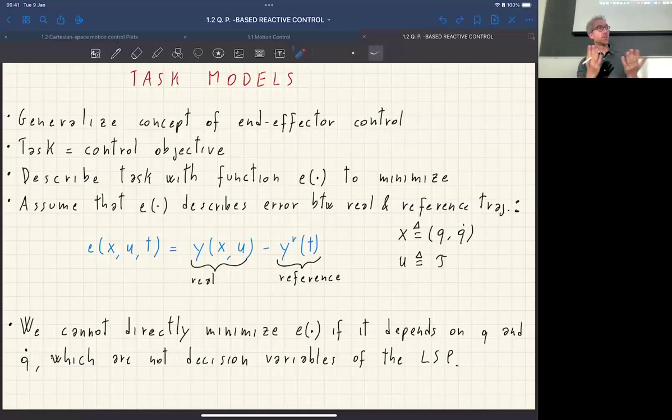In particular, we have seen how we can generalize joint space inverse dynamics. And the generalization mainly consists in adding inequality constraints to the problem. These inequality constraints we can use to represent the motor torque limits, the joint velocity limits, the motor current limits.